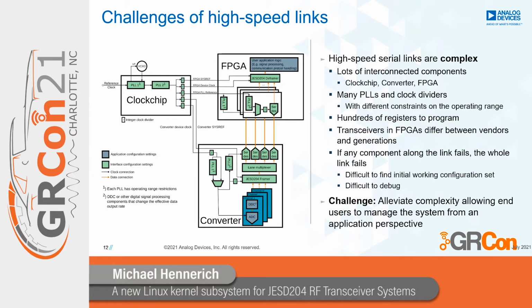So the system looked relatively simple until now, but in fact each component hides hundreds of registers. There are several PLLs and vendor-specific high-speed transceivers which the user needs to program. So this suddenly does not look like an easy task anymore. And also debugging such a system is difficult, especially since if one component fails, the entire link fails. So the challenge is to mitigate this complexity and allow the end user to manage the system from an application perspective.